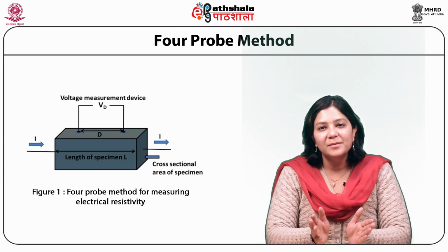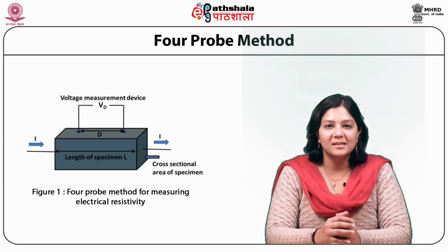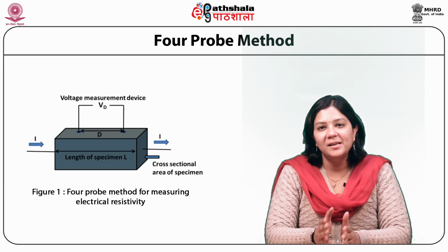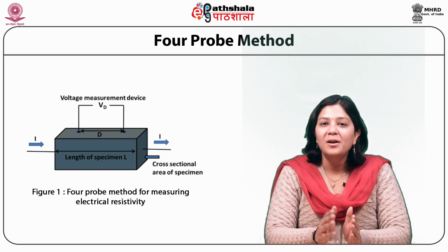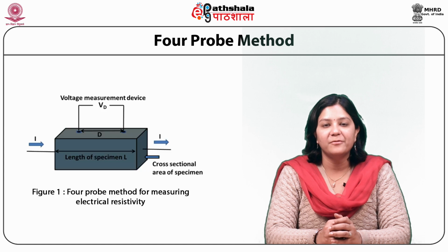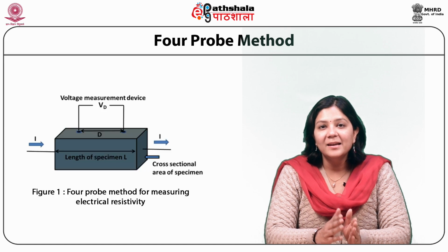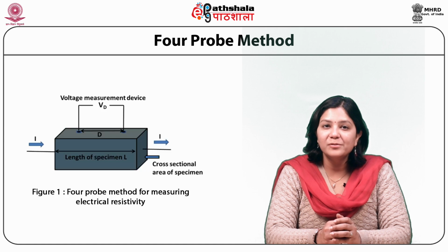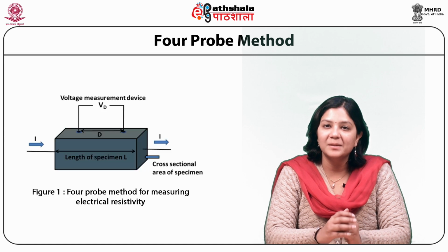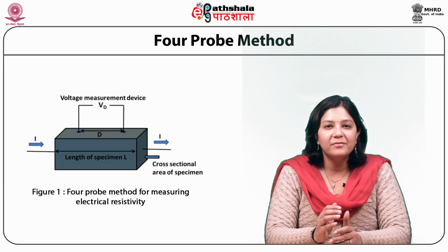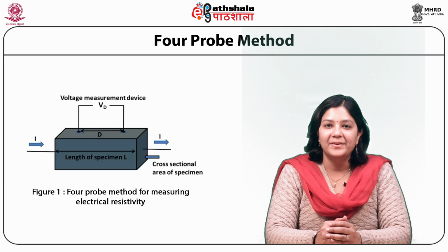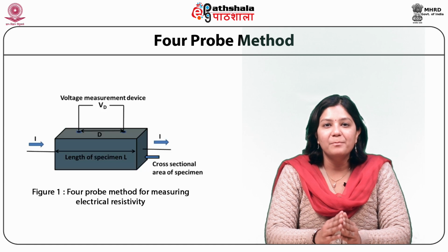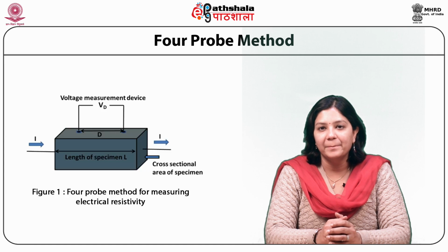Though the contact and the probe resistance themselves are cancelled out, there is still a possibility of error in measurements if the contacts produce heat. Therefore, low resistance of contacts is preferable. The error due to DC offset in the instrument is readily overcome by subtraction. Additional self-induced voltage offsets within the circuit can increase the error. This may be rectified by flowing reverse current in the sample.